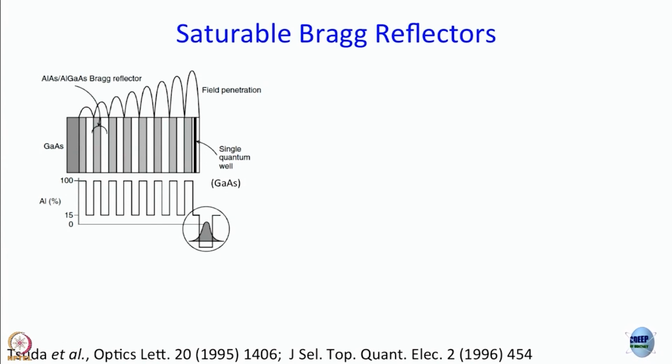So, right now what everybody wants to use is solid state solutions, and something that is used very often is a passive mode locker. What is used is a saturable Bragg reflector, which acts as a saturable absorber and therefore a passive mode locker. But I should explain what a saturable Bragg reflector is. Even before going there, I should tell you what a Bragg reflector is.